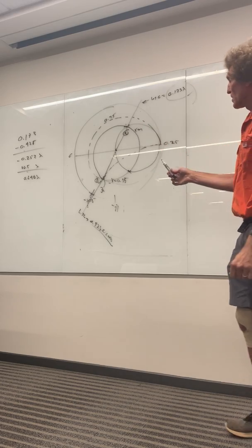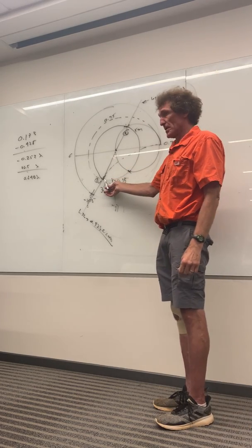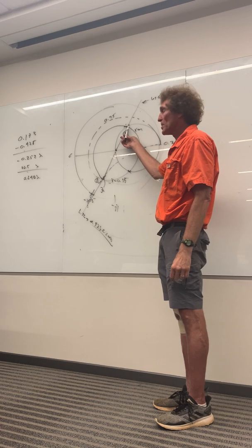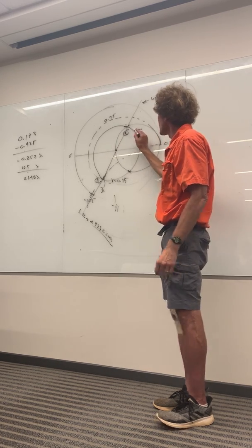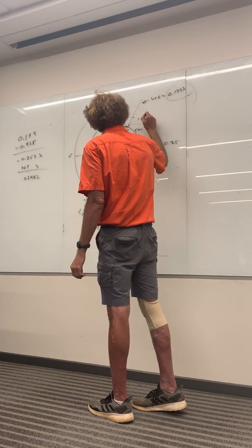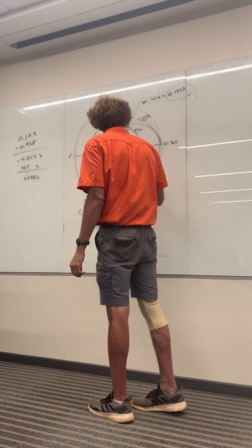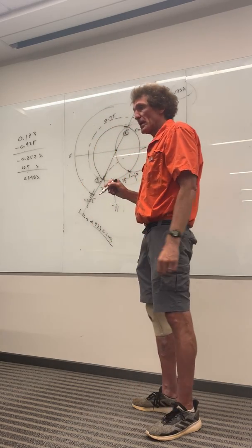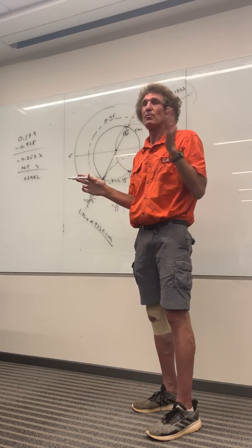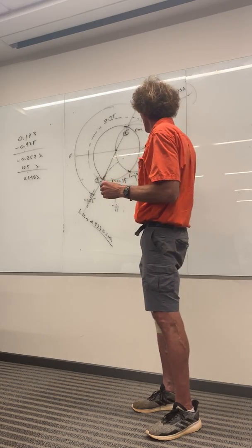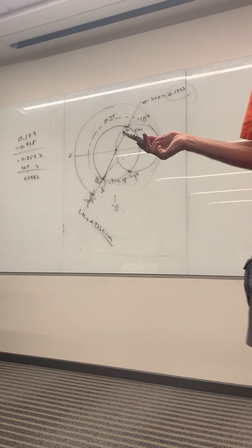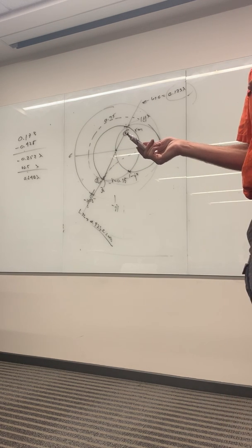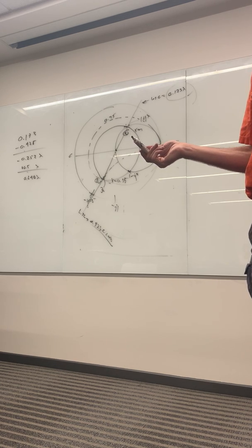No. All right, look, this is the point we started at. Do you agree with that? Yeah. This is the point we want to go to, right? How did we find the point we want to go to? Because it's 1 plus something. This is going to have 1 plus jx, and this is 1 minus jx, right? Oh, okay. And we want to go to the point where the real part is 1. So you want to intersect the 1 circle, and the reason we want to intersect it is because we can get rid of that j term by adding an element. Then the input impedance will be just Z naught. Do you follow me on this?